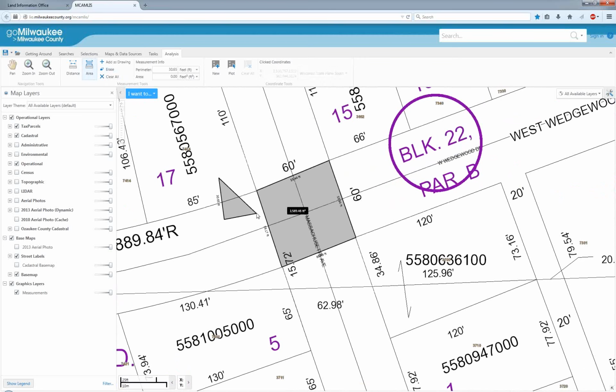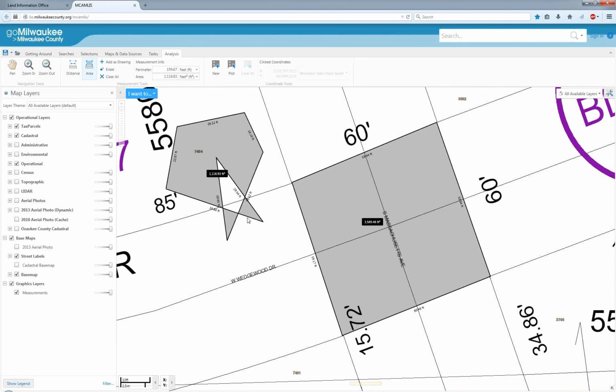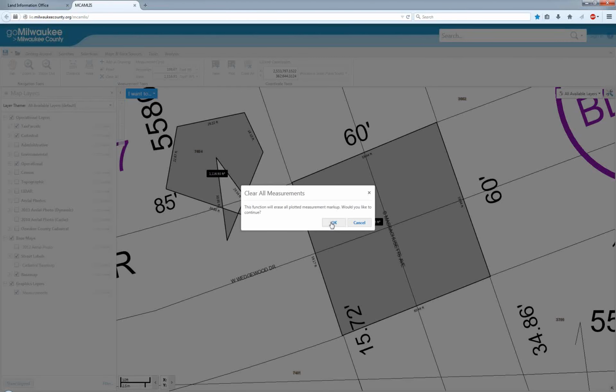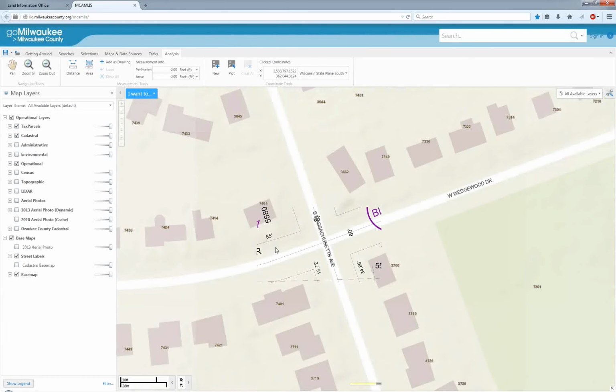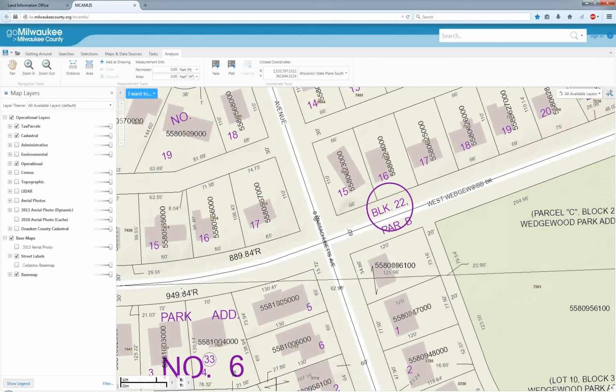Let me draw area again. So, and oddly enough, if you draw over a measured area, it'll kind of invert this space here. So there's not really any reason to do that, but it's something to watch out for. It'll do the calculation and actually remove this space. So I just would recommend avoiding that altogether. So that's the measure tools. They're all really simple. It's basically the easiest, quick, and dirty way to get a measurement.